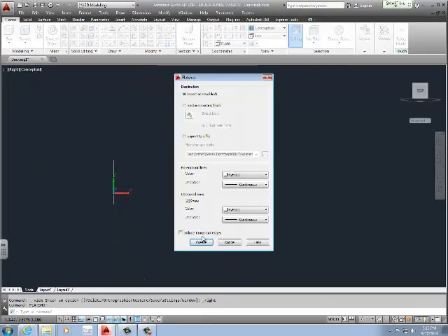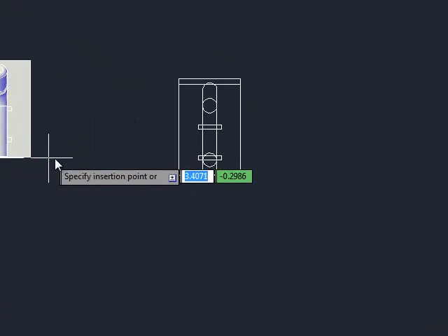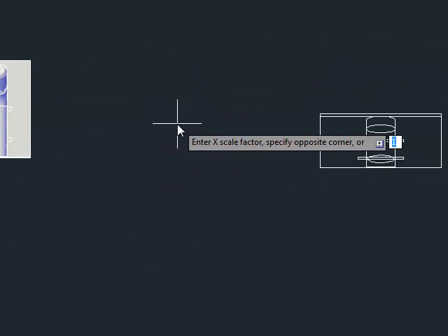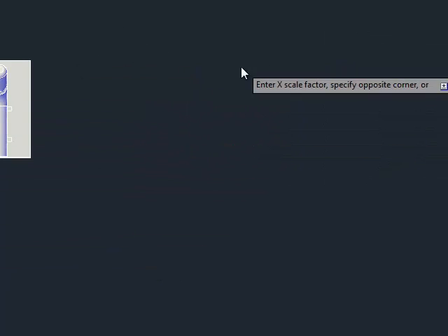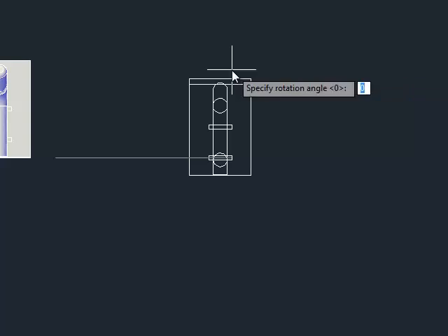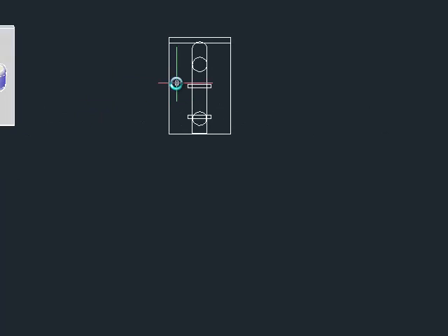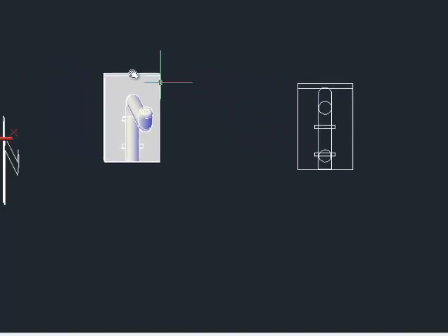Create as a new block, so you can place it somewhere on the screen, away from our main 3D part and our 2D vertical part. And we're going to type in enter for the 1:1 scale, and the X to match the Y scale. Now technically you didn't have to do that first part. Actually you do have to, because we have the bottom and the top dimension, but we don't have the side, the front, so we have to use the top as a reference.